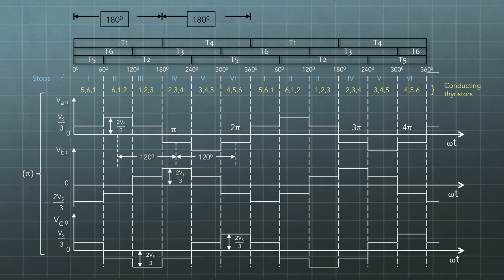This can be implemented for each switching operating region, and you can see that the waveforms are taking the shape of an AC. Here you can also see the waveform representation of the line voltages, which clearly shows that you have converted the DC into an AC. Therefore, we have successfully implemented a 3-phase inverter that will be operating in 180-degree conduction mode. Hope you have got a good insight on the operation of the 3-phase inverter, and the 120-degree conduction mode can be discussed in another class.